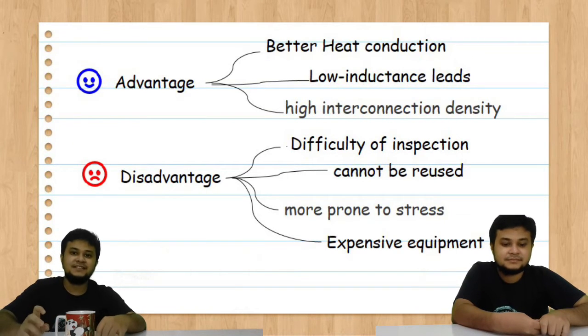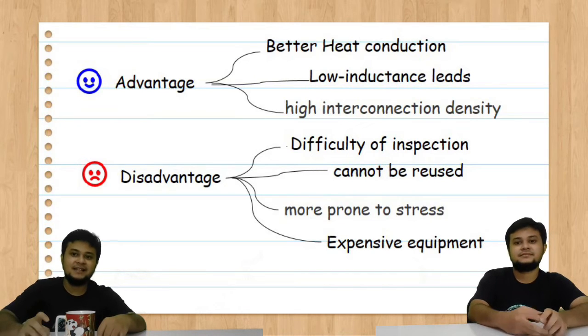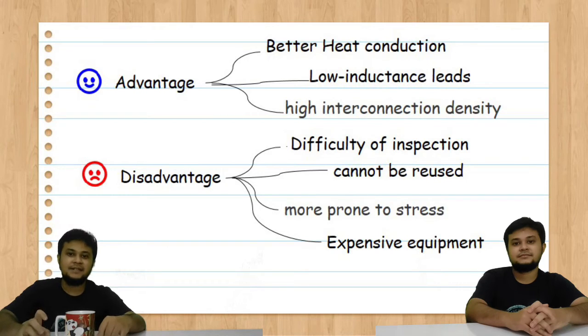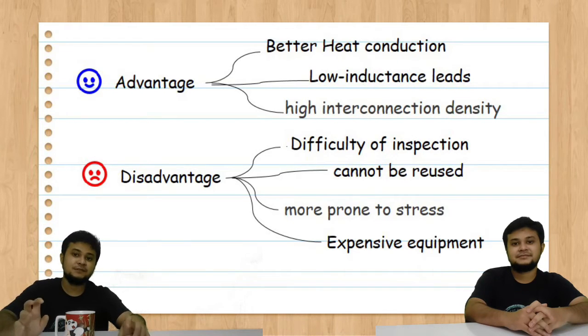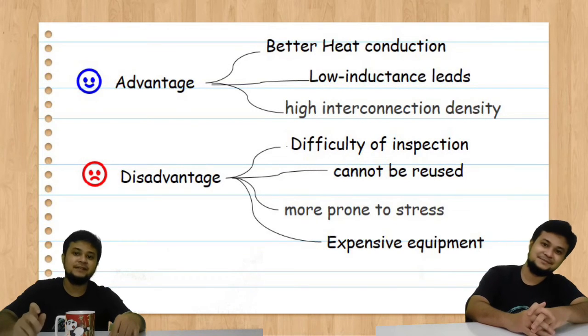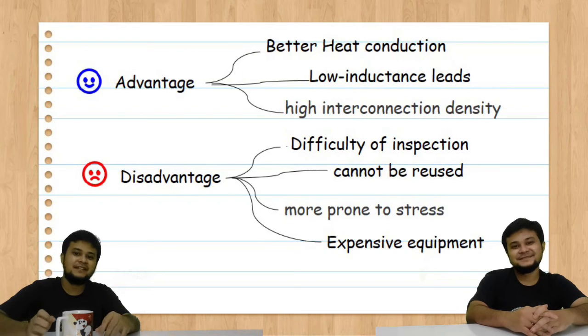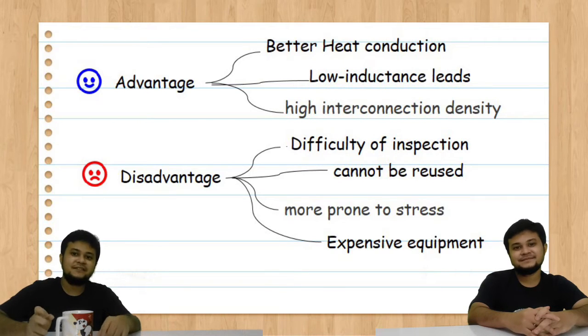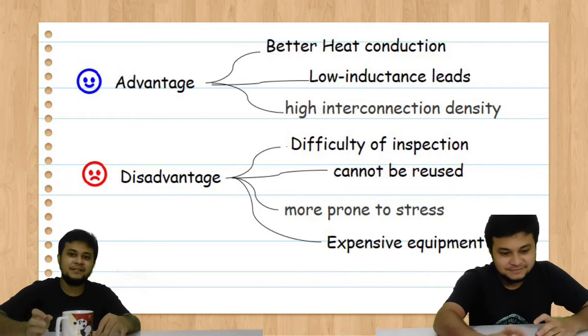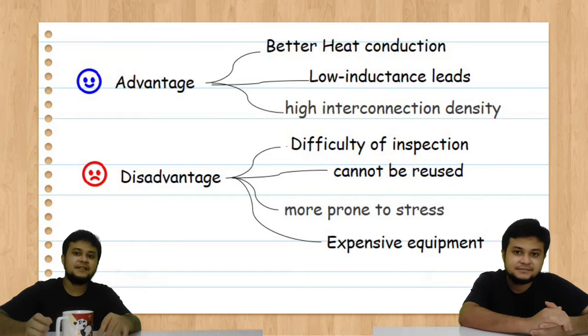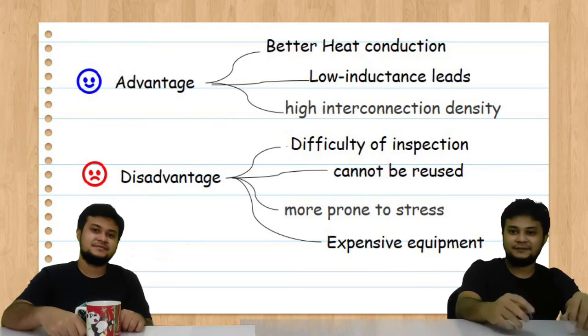When they have a short distance between package and PCB, the inductance will decrease. The electrical performance becomes better. BGA, with their very short distance between the package and the PCB, have low lead inductance, giving them superior electrical performance to pin devices. Third, high density. BGA is a solution for production of miniature packages for an integrated circuit with hundreds of pins. BGA does not have the common issue of adjacent pins bridging together when the solder is factory applied to the package. Thank you for the advantages.